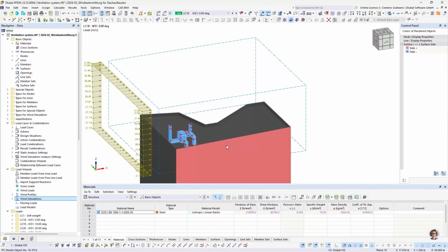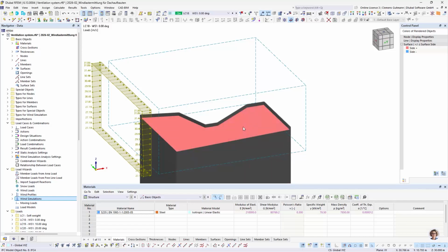So if I have a perfect geometry, like my building here, it's an IFC file, but it is completely closed and, let's say, ready to calculate structure, there no shrink wrapping is needed, and hence it will not be created for these objects. So if I have a perfect geometry with my static analysis model, for example, if I have one simple plate or sheet, let's say, it's a perfect box, so there's also no shrink wrapping needed.